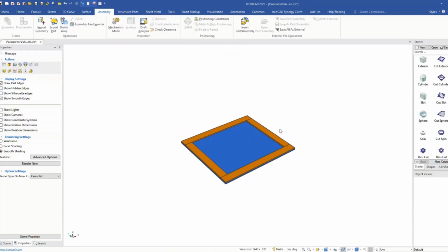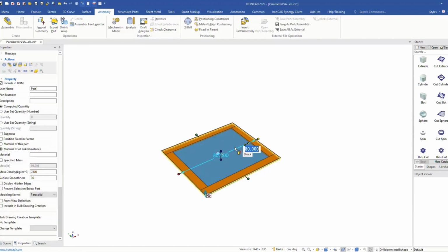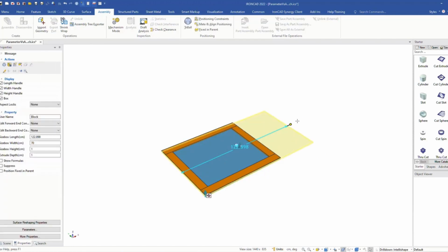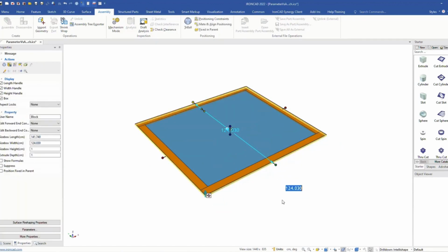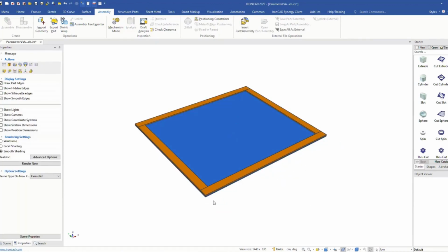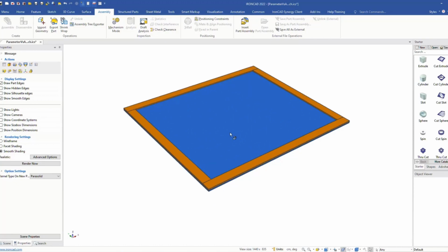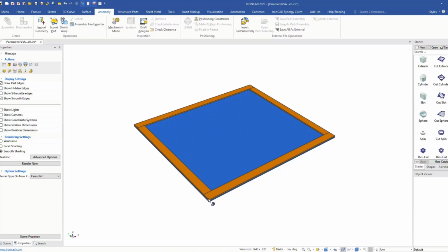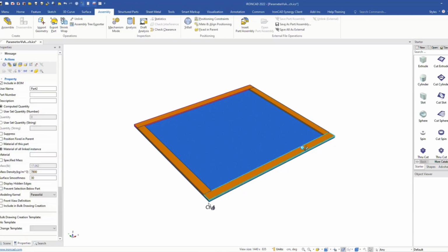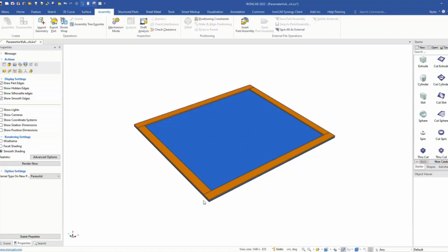We've essentially got this thing set up parametrically, and we can now go to our block and adjust this, and we can see that will update that direction, and this will update this direction. Okay. Fairly straightforward, fairly simple to do with parameters. This is a simple example, but it just gives you an idea. And this part is coincident, and only one constraint was needed. You could have done mates, then aligns on these edges, things like that. But you could do it with a coincident constraint in this case to make it simple.